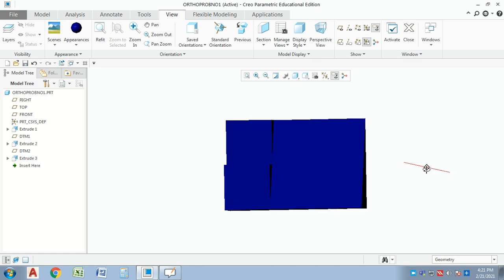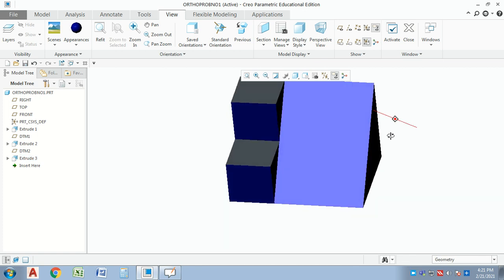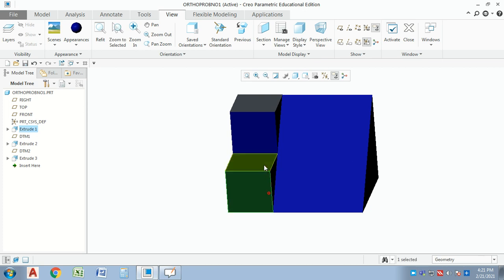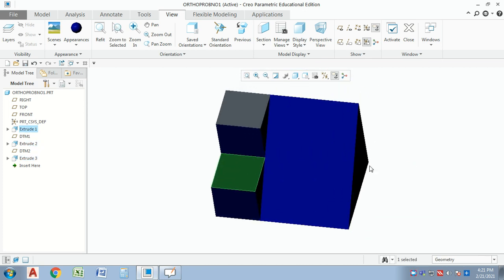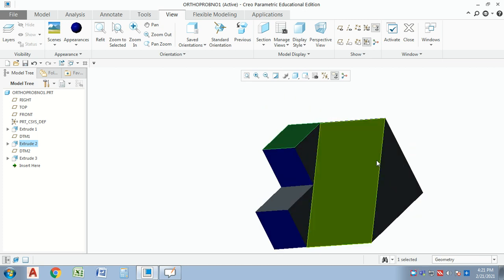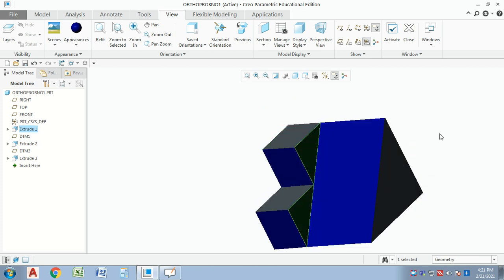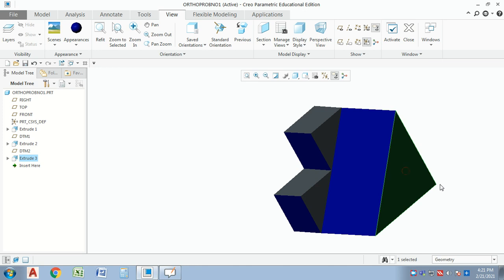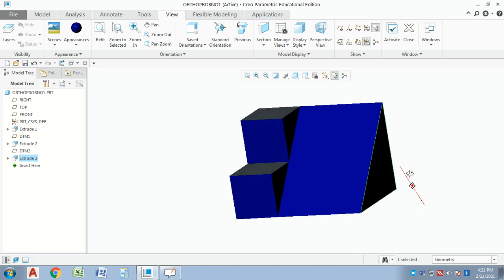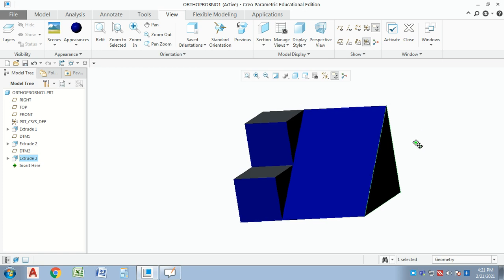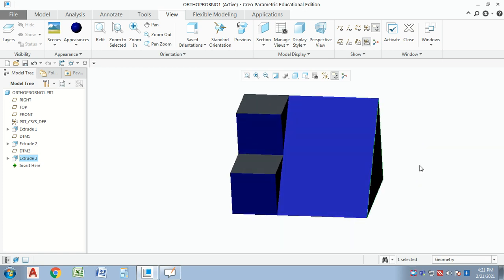It will become like this, a single color will come, because these three faces are visible in front view: this one, this one, and this one. The rest, this face is visible in top view, similarly this, and these two faces are visible in side view, and this one is also in side view. Now we have to start the front view stepwise. Now see this corner. This corner will be the start point for us.